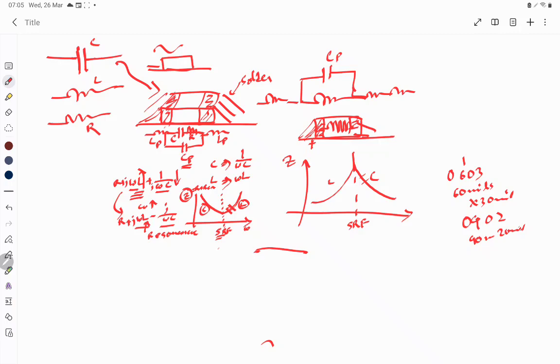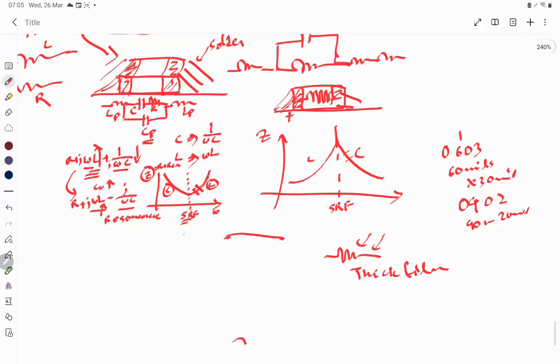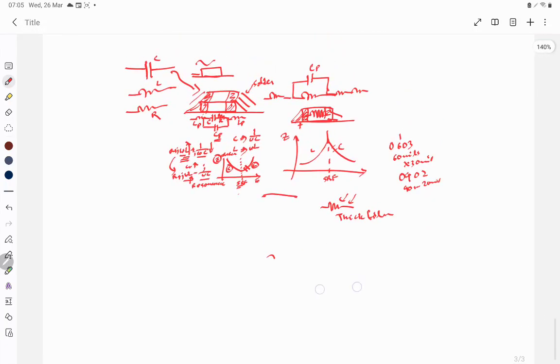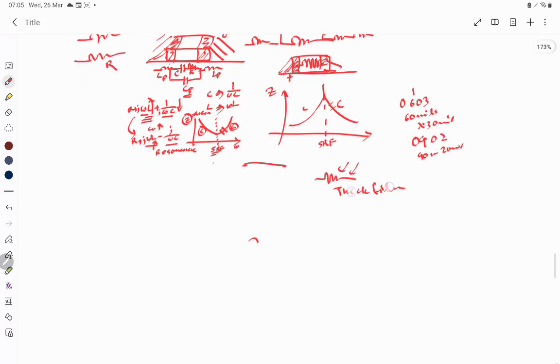A normal, simple thick film resistor might stop working even at 2 gigahertz or 3 gigahertz, because some inductance or capacitance, the capacitive reactance, will take over from its pure resistive form. So it is very difficult to use lumped components at these high frequencies.